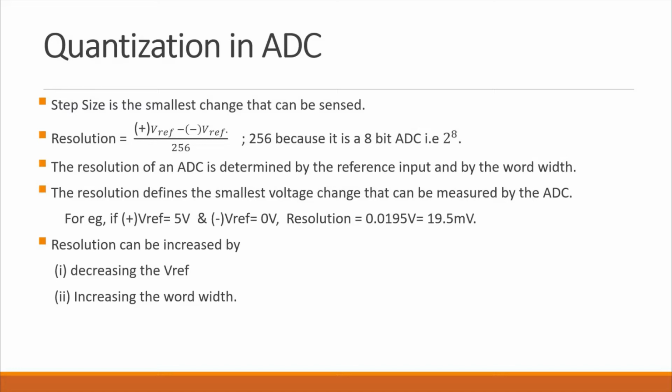That analog voltage or current will be sensed by this ADC and converted into a digital value, and that way you will get your temperature. Clear? Right. But suppose there is a temperature change of a very finite value. Let's suppose that at this moment the temperature is 25 degrees Celsius, and after a certain period the temperature changes only by 0.01 degrees Celsius. That's a very negligible amount of change in temperature.